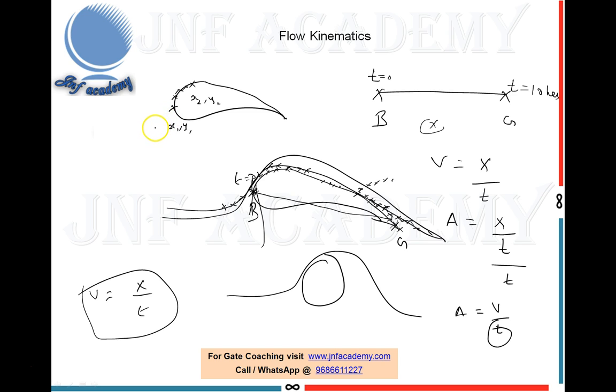Because of this, taking the derivative with respect to time for the fluid particle is not as straightforward as we have seen in the car case. We also need to consider any change in flow not only with respect to time, but also with respect to space, because the fluid particle will get convected as it moves through the solid object.